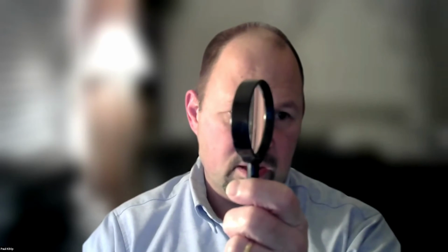So if you phase an antenna, like you have 2 loops and you phase one 90 degrees out the other, how do you do it 90 degrees? You take 90 degrees piece of coax, which is a 1/4 wavelength. So you build one antenna, you build a second antenna, one this way, and then you run your coax to one, and then you run a 1/4 wave jumper to the other one. And now you just phased them 90 degrees out of phase, and that becomes a circular polarized antenna.